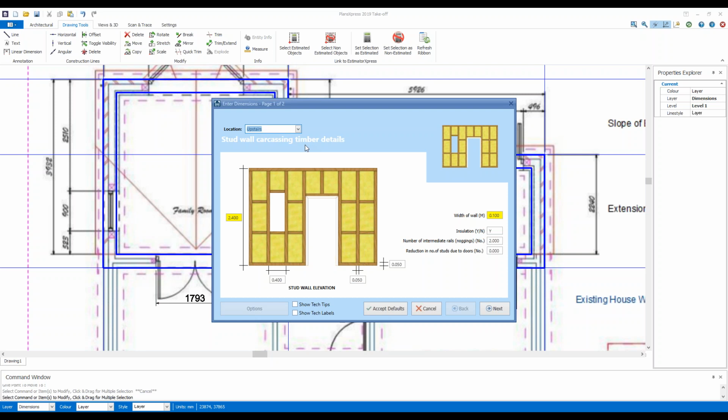estimate later on. If I had selected, let's say, a brick and block cavity wall like I did before, but I had chosen additional floor rather than ground floor, then it would have automatically zeroed out foundations, footings, and that would have affected the cost. But no, the location is literally just for your reference.